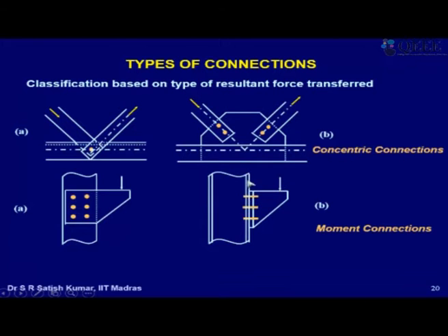So this load will of course cause some shear in the bolts, but apart from that, the bending moment will try to put more tension in the upper bolts. So these bolts are under tension plus shear, and that has to be accounted for. The extra tension will depend on this eccentricity, from the face of the column or the shear plane of the bolts to the loaded line, where the load is actually acting.